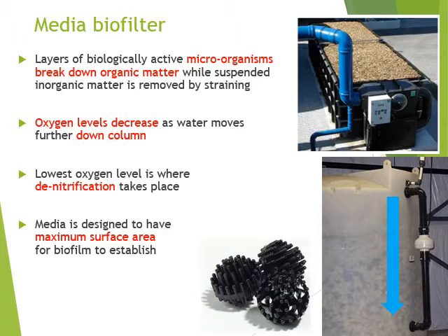A lot of the organisms, Paramecium, Vorticella, whatnot, they actually anchor onto a structure. Even amoeba, they don't like to float. They usually crawl on a surface or attach to a surface. So in order to support those beneficial organisms, we want a large surface area so we can support a lot of those microorganisms. And then we'll have more bacterial growth and more consumption of pathogens and nutrients, right?